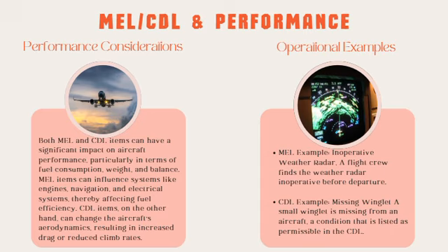Operational examples of MEL and CDL impact on flights. MEL example: inoperative weather radar. A flight crew finds the weather radar inoperative before departure. According to the MEL, the radar can be deferred, but only if the flight will avoid areas of known or forecasted adverse weather. The crew adjusts their route to avoid thunderstorms, ensuring passengers' safety while still completing the flight.